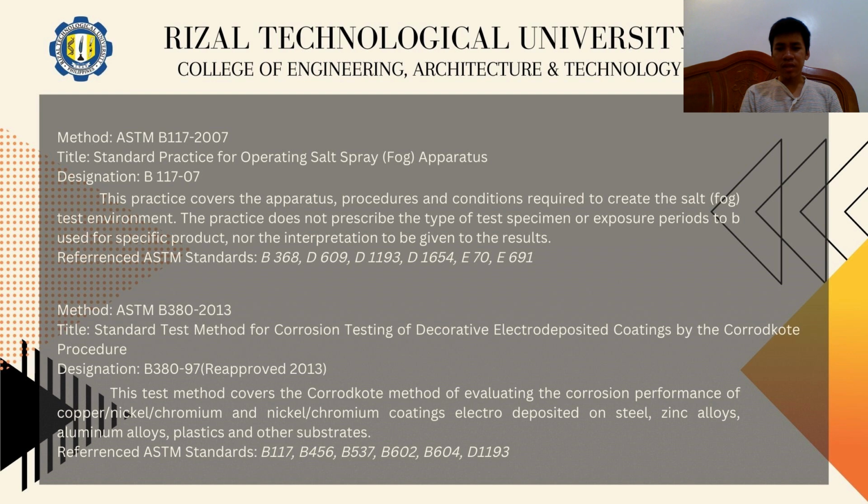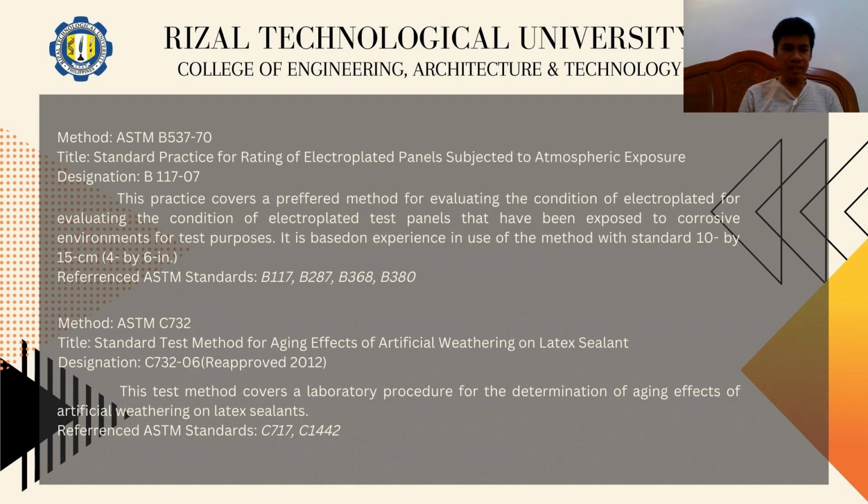It is significant as the Corrodkote test provides a method of controlling the quality of electroplated articles and is suitable for manufacturing control as well as research and development. Nickel, chromium, and copper, nickel, chromium electrodeposited coatings are widely used for decorative and protective applications. Next is ASTM